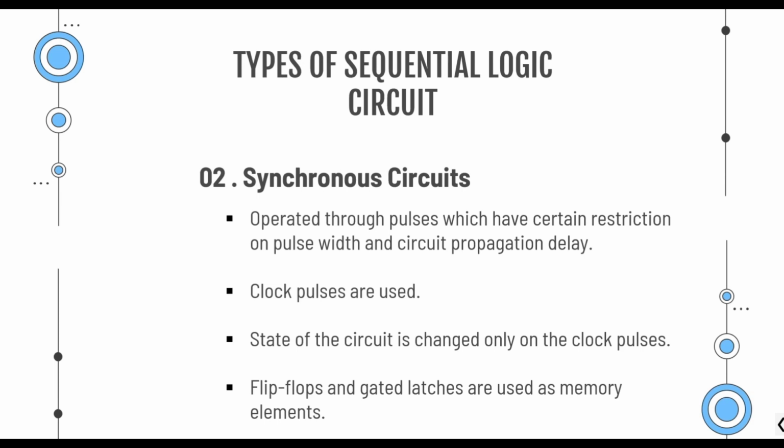And there are some disadvantages. Synchronous circuits are slower than asynchronous circuits. The reason is that the maximum possible clock rate is determined by the slowest logic path in the circuit, which is also known as the critical path. The logical calculation from simplest to most complex must complete in one clock cycle. So the logic paths that complete their calculation quickly are idle much of the time waiting for the next clock pulse. Therefore, synchronous logics can be slower than asynchronous logics.